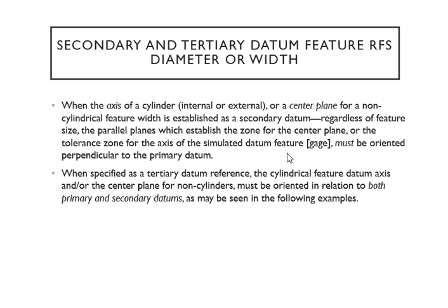Since we are talking about it, sometimes your brain is cluttered with all that new information, so you can't see it very easily. But it's very simple. It's trying to find the axis, and we call that the datum feature. In order to find the axis, you have to use a simulated datum, which is actually a tool. We try to use the different planes to locate the center. So that's what we do in each of the examples. Of course, we throw in secondary and tertiary datum as needed, depending on the part and the function.